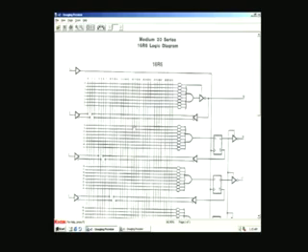The design we have now completed can be fitted into a programmable array logic. The choice of the PAL is important. It needs registered outputs mainly, because all of these are registered outputs. There are states B, C, D, E, F, all of them are registers, and their outputs are also state outputs. So we need registers, and we also need a combinational output because of the clear signal.